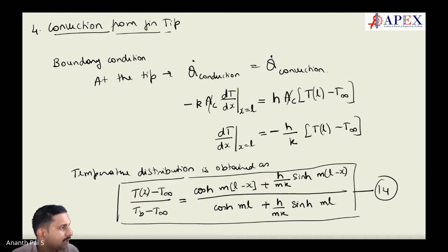Correct. Third one, the final part of the fin is maintained at a particular temperature. That can happen. The fin can be between two pipes, where on one side one temperature is there, on the other side another temperature is there. That's the third case. Fourth case: it's not a long fin, it is not insulated. So from there can be heat transfer. So then what?